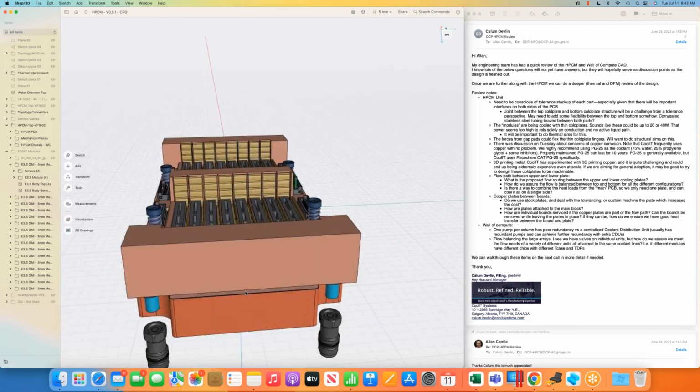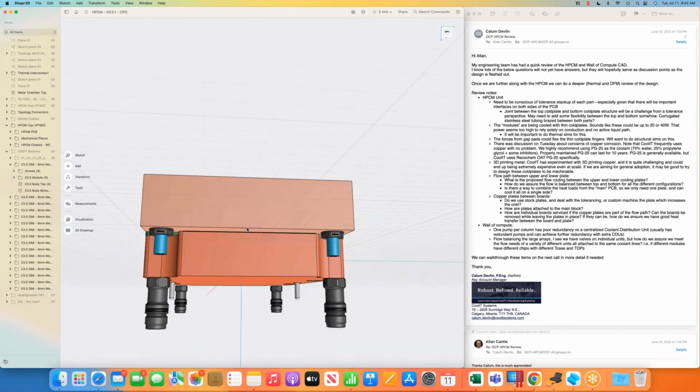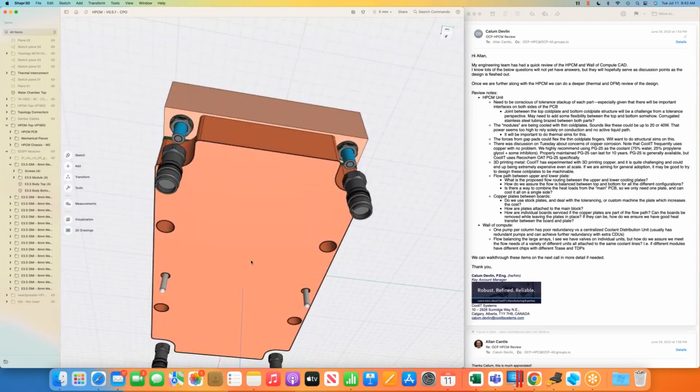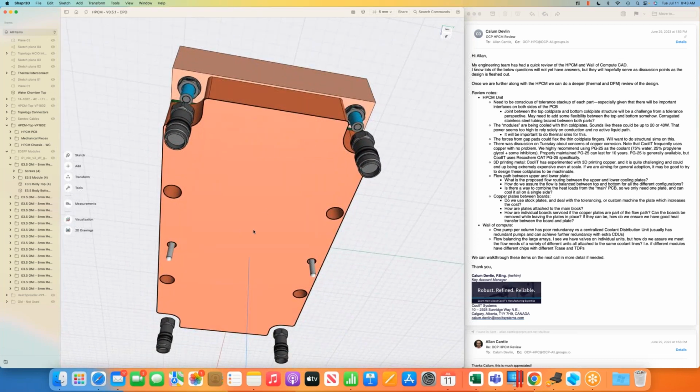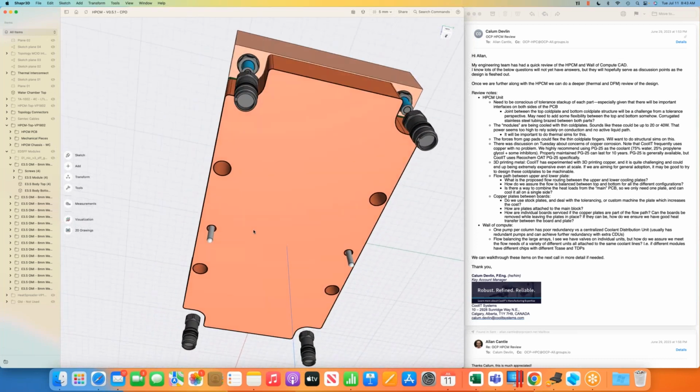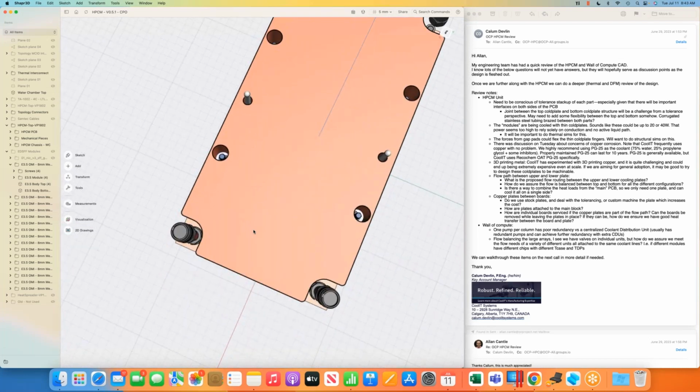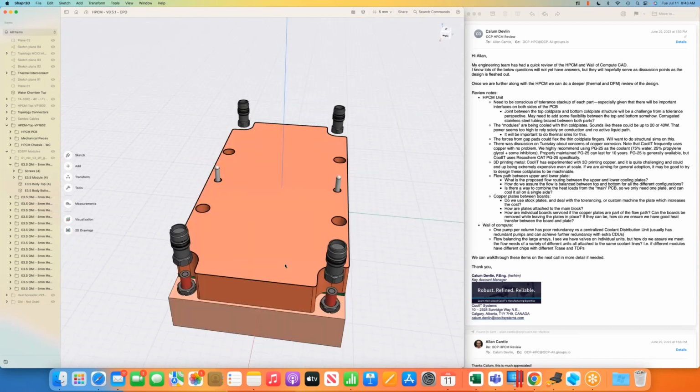We don't show the interface, this is what we were discussing earlier, then it would transfer to the top coolant area and flow across the 1 kilowatt GPU, CPU, switch, whatever, and then it would come out of these hot ones. And then it would be at 65C if the flow is controlled coming out of the big processor.